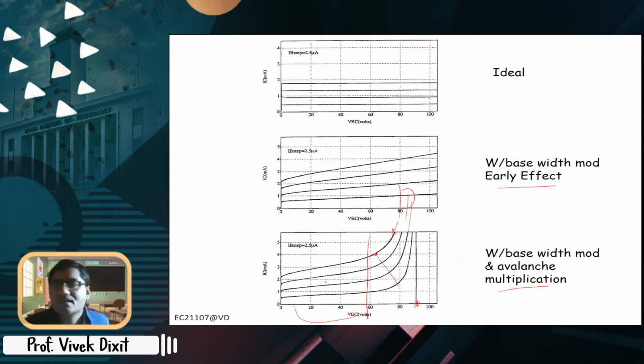So if you see in your lab, there is a limit to VCE, right? Now this is the limit here. So of course we don't go to that voltage anyway. We usually keep it around 12 volt or something, right? So we are well in the safe limit. So far, any question?